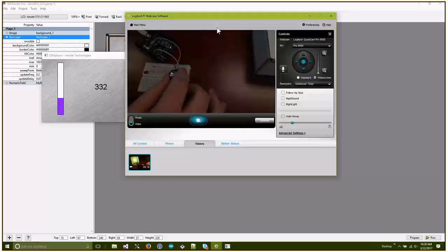So there you can see it's pretty easy to use it in either the slave or the master mode, or even a dual master. If you want to write commands to the Arduino, for example on a button push, write a command to it, and then from the Arduino side, when you have new sensor data, push that up live on demand without waiting for the Amulet to poll for it. It actually reduces the traffic on the UART, because instead of polling, you just do things on demand.